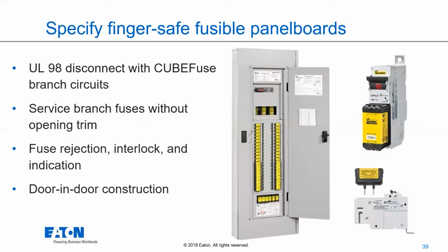You can also specify, now we're getting back here, finger safe. Finger safe doesn't necessarily help you with arc flash, but it will help you with that electric shock hazard, right? Finger safe products are always very, very good for that.